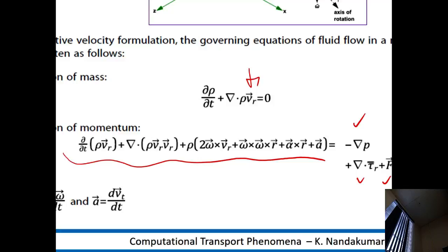A centrifugal acceleration, omega squared R, right? And this is omega times dr. This is called a Coriolis force. These are forces arising out of the fact that we are in a reference frame that is moving. These forces are important in geophysical fluid dynamics. The jet stream and the Gulf Stream in the oceans are all governed by these terms. Here, this is the Earth's rotation, for example. So these terms arise and are important in certain flow configurations.